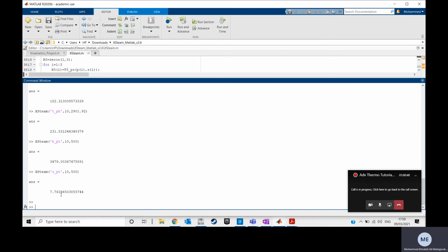So you go to table A5, and you say, I have 10 kilopascals for the lower pressure. Then I need to check this value of entropy. So when it is between the saturated values, it means that this point is probably going to be a mixture. Of course, this is not the actual point, this is the isentropic point, but it's going to be somewhat close to it.